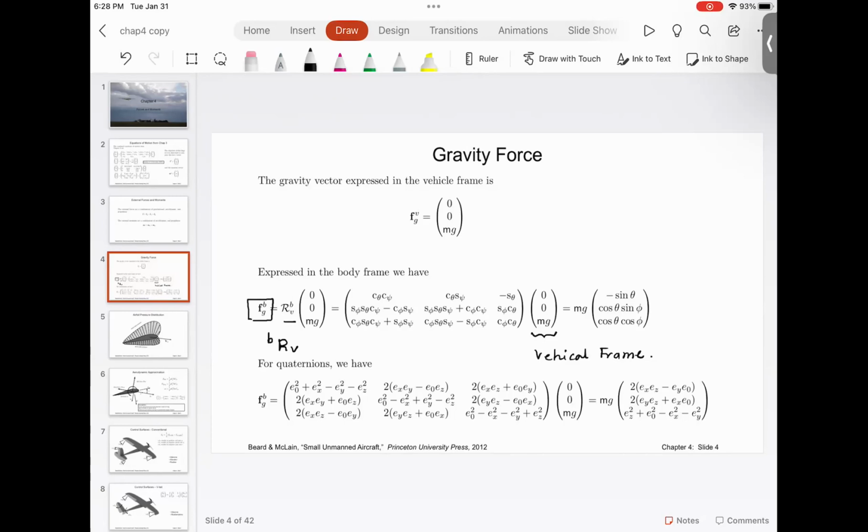But the gyro will give you a better estimate when the aircraft is moving fast. So what you do is you adjust the weights to the roll angle computed by the accelerometer, and you add the weight multiplied by the roll angle computed by the gyro and combine them together, and that gives you some type of a complementary filter, and that works very well for the MAV or simple flying robot application.